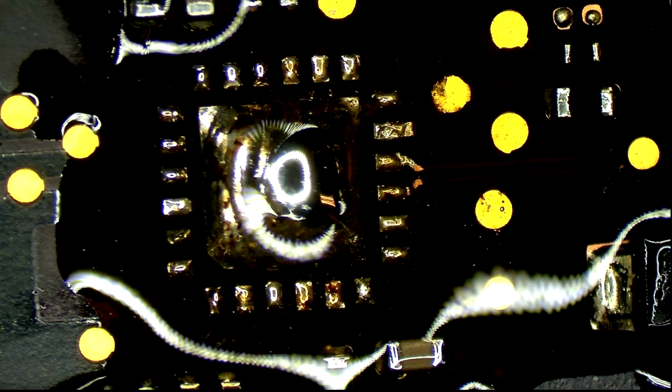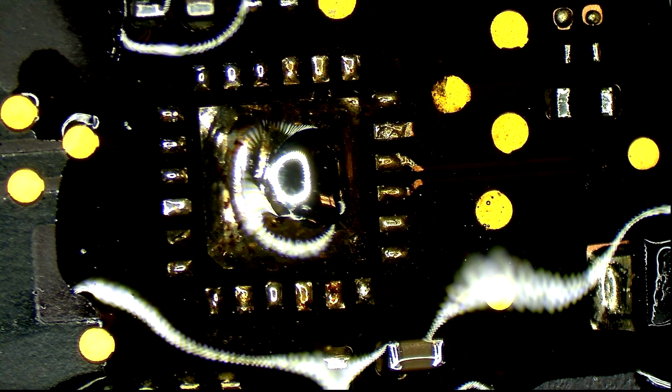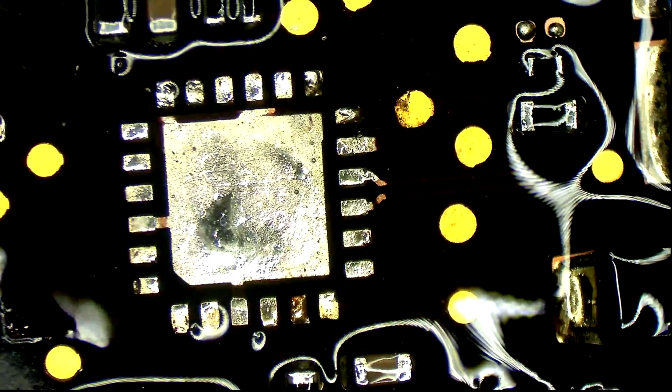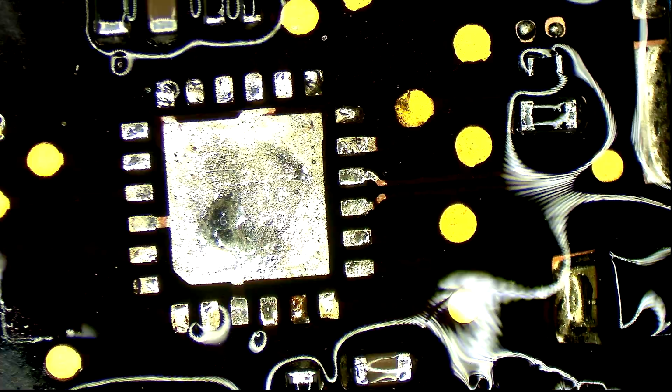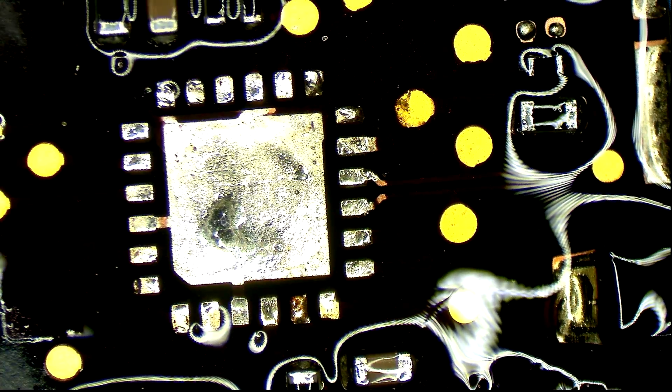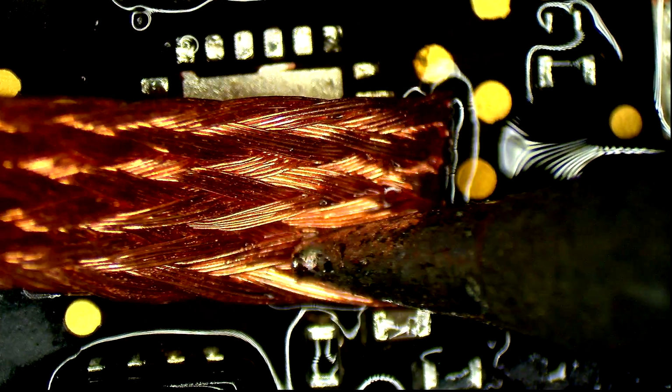I learned how to wick from Jessa at Practical Board Repair School before going off and starting my own tutoring service at the store. Jessa said, I want you to be successful with everything you do. And for that, as a thank you for the time you spend teaching, I'm going to show you how I fix every motherboard here at iPad Rehab. She told me not to tell anybody that it was a secret, but I've decided that I can't leave it as a secret anymore. I need to tell all of you. The secret to Jessa's success has been that she wicks every pad on every BGA IC that she ever replaces. Even if it doesn't have solder on it already, she wicks it for good luck.